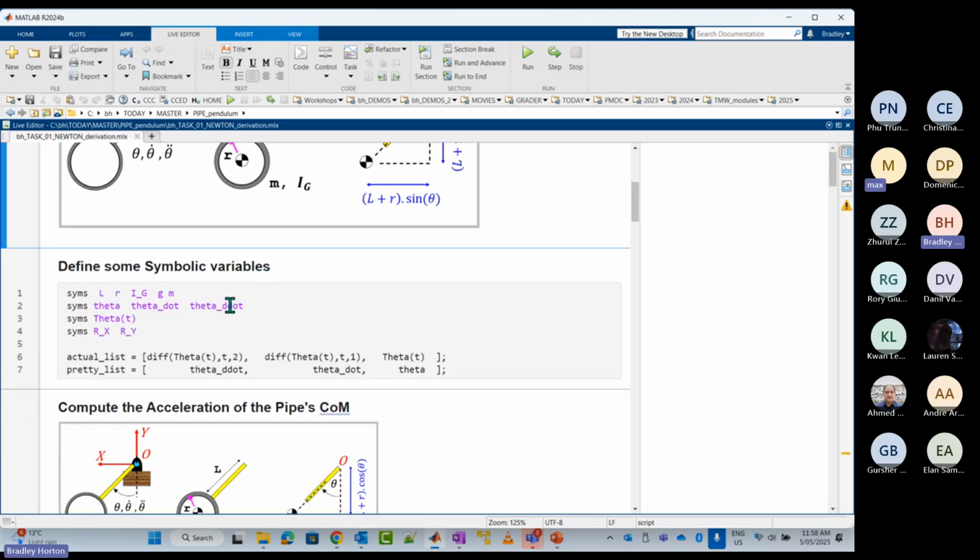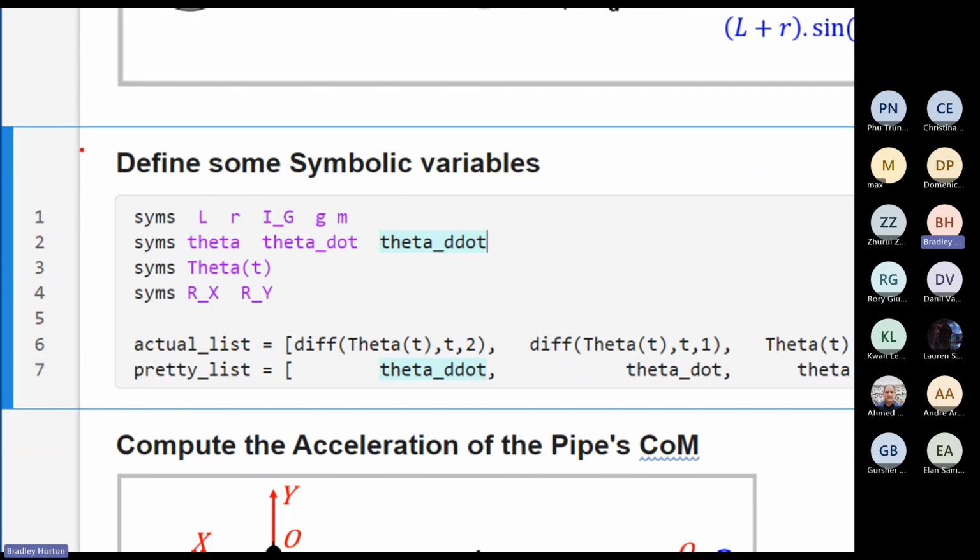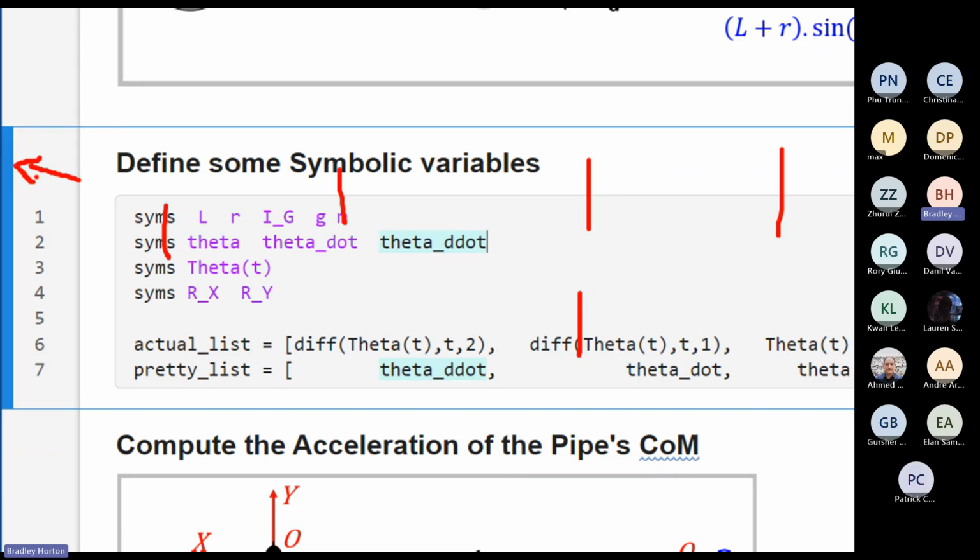So as I scroll down the script to this very first section, let me get you orientated. I'd like you to scroll down until you get here, and again, just click anywhere inside this part of the script. When you've done that, you'll see that over on the left-hand side, there's a little blue vertical strip. The fact that it's blue is giving you feedback that this is the currently selected section in the script file. Now, that blue strip, besides giving that nice bit of visual feedback, if you click on it, it will run the code just in this designated section.